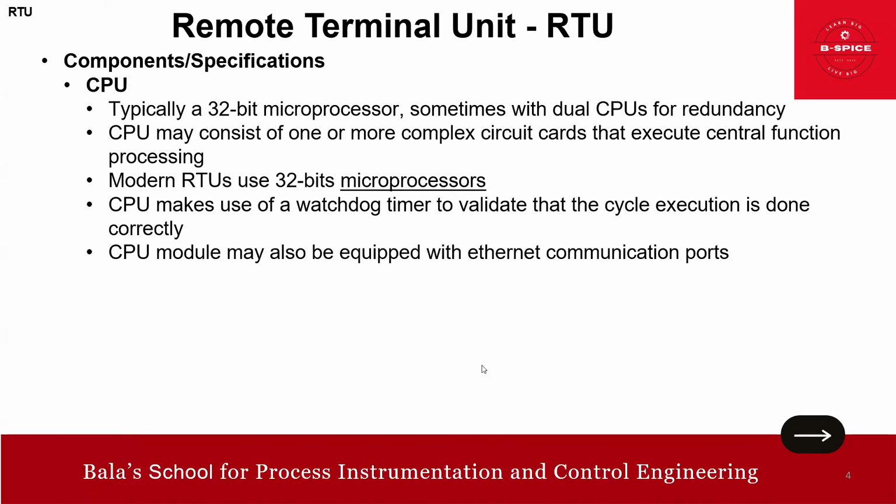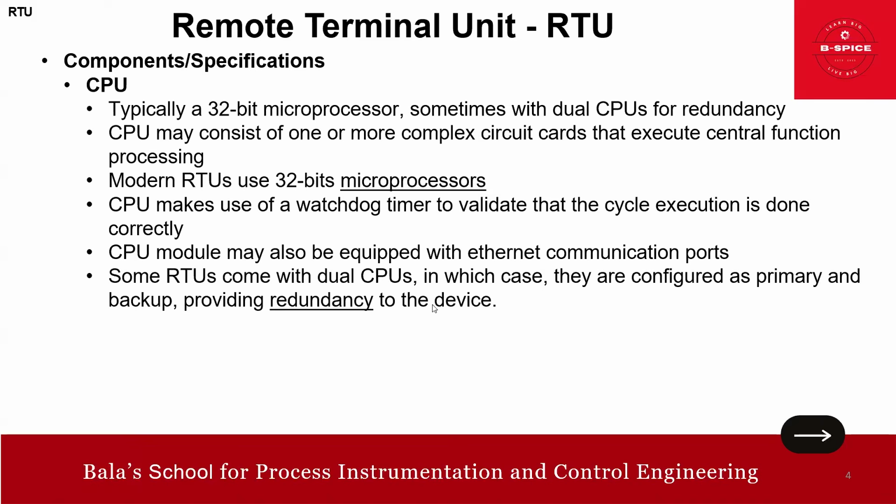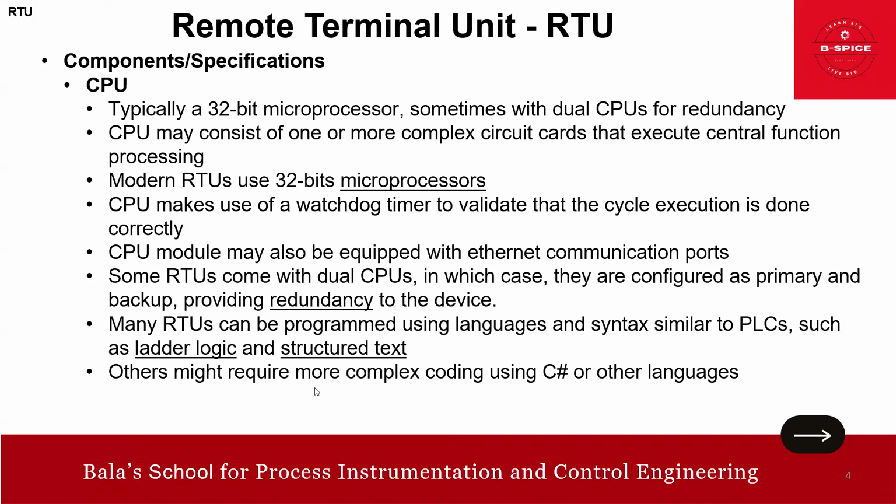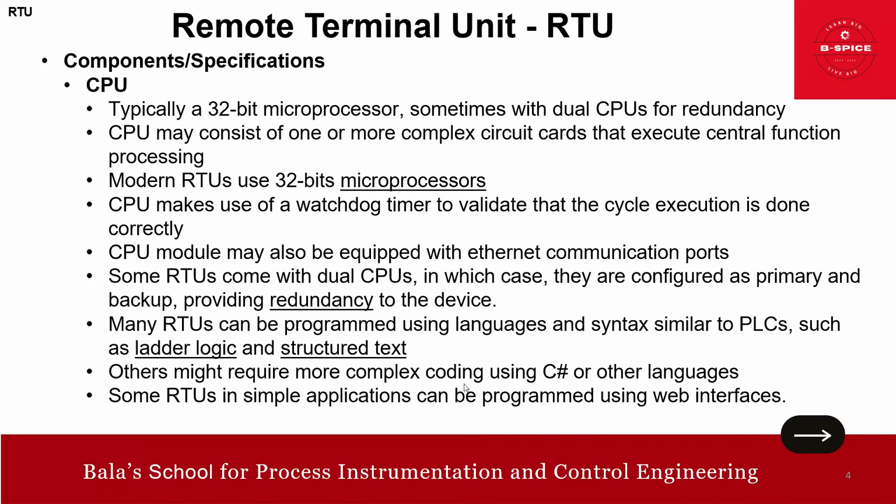Okay. And the CPU module is also equipped with an Ethernet communication port. Some RTUs come with dual CPU, in which case they are configured as primary and backup, providing redundancy to the device. This is based on your need. Many RTUs can be programmed using languages and syntax similar to PLC, such as ladder logic, structured text, etc. Others might require more complex code using C++ and other languages. Some RTUs with simple applications can be programmed using a web interface. So these are the aspects about the CPU.